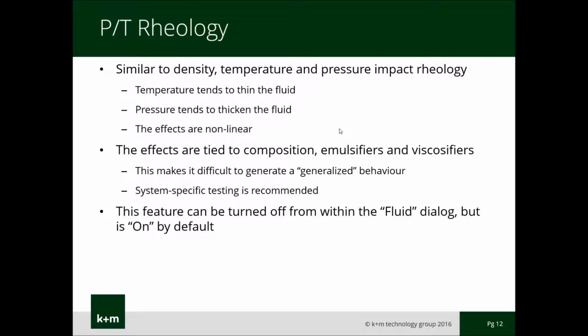ERA features a number of generic characterizations of fluid rheology at temperature and pressure. But for the most accurate results, it's best to perform HPHT rheometer testing on the specific fluids that you are using or planning to use. The HPHT rheology corrections are turned on by default in ERA, but can be turned off in the fluid dialog, which I'll show you in a moment.